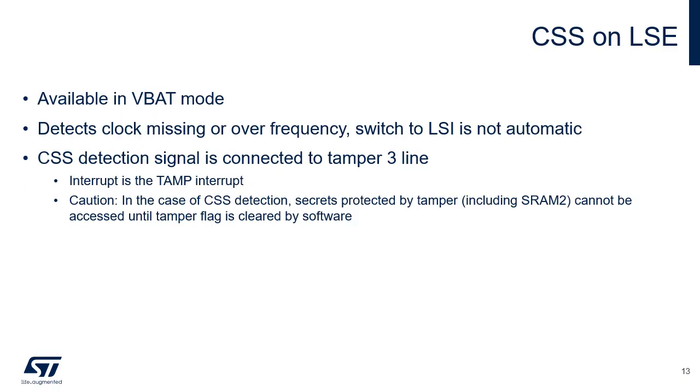A clock security system monitors for failure of the LSE oscillator. It detects a missing clock or over frequency. The CSS on LSE works in all modes including VBAT. It's also functional during system reset, excluding power on reset.